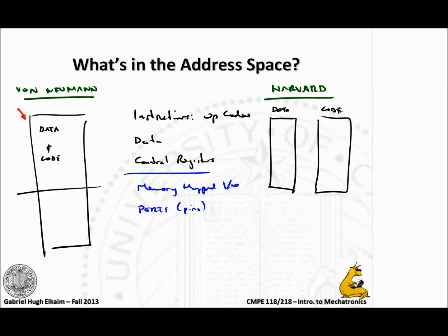it happens. Now if you're not doing space qualified stuff, you don't need to worry about it too much because we don't get too much cosmic radiation down here, so we don't have to worry about single bit upset events. But they do happen.